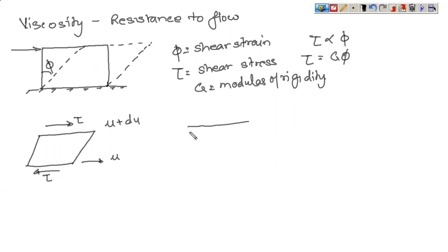So let us say that this is one streamline of a fluid, this is another streamline, this is another streamline. Each fluid layer is actually sliding one over another so that flow is maintained. So beneath it, there will always exist a plane which is not sliding, which is stagnant. Planes above it have different velocities of sliding, and the topmost layer is sliding with the maximum velocity. The reason is that the forces are applied tangentially, that means onto the topmost layer of the body.